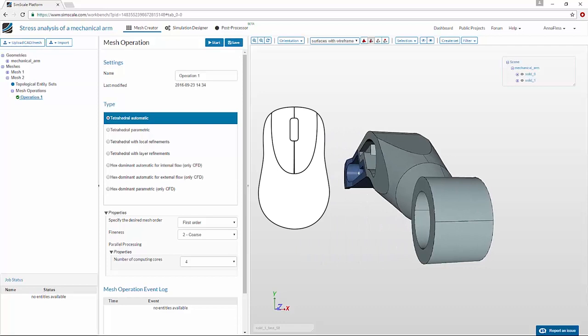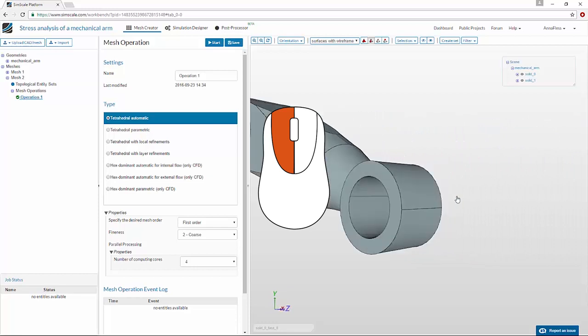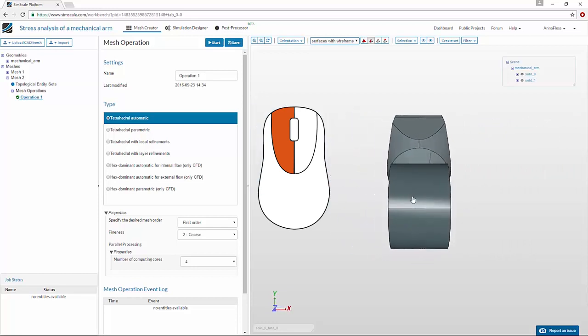The default center of rotation is set at the axis origin of the CAD model. In order to change the center of rotation, hover the pointer over the desired face and double-click. The anchor point for the viewer rotation will now be pinned to that face.